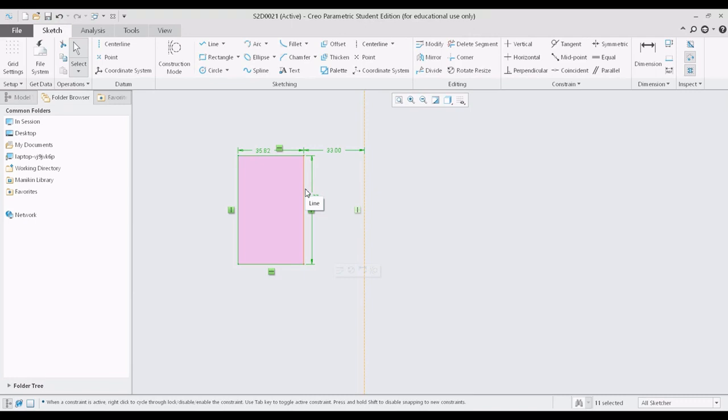Like for example, if you consider a car, you have side view mirrors on both the sides. So side view mirror is a feature in the total geometry, and it is placed on both the sides, symmetric to the vertical axis. And imagine if you're designing a car with a side view mirror as the basic feature in the total car, and if you want to mirror that feature on the right hand side, you have to use the mirror option. So in that case you have to select the feature first, as I'm selecting the rectangle in this case. Then you have to click on the mirror option.